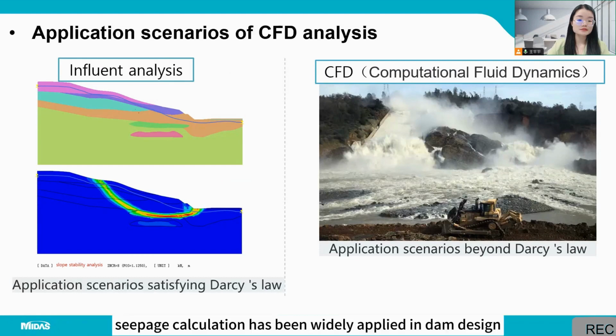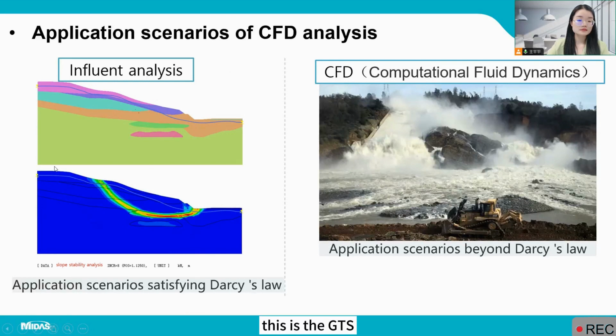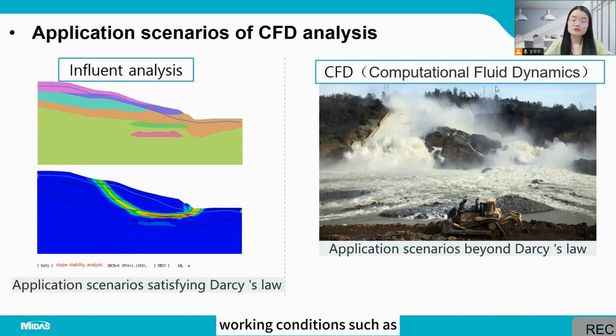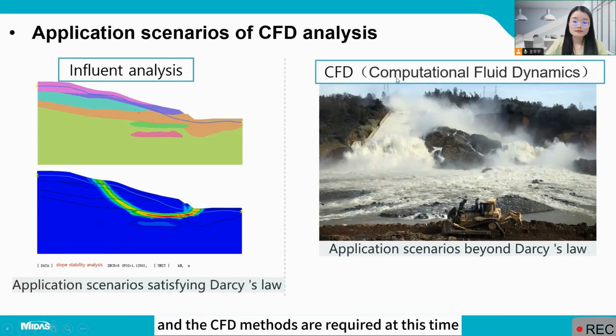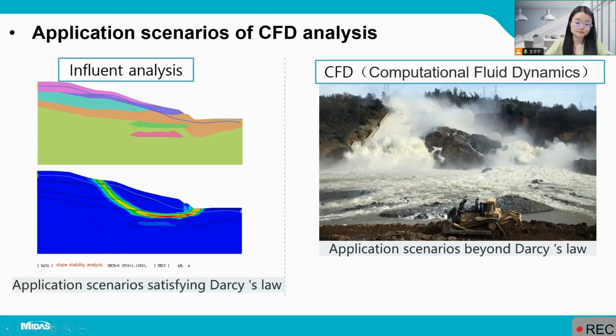Similarly, seepage calculation has been widely applied in dam design. This is the GTS. But the premise is that Darcy's law needs to be met. Working conditions such as dam break and flood discharge clearly exceed Darcy's law, and the CFD methods are required at this time.